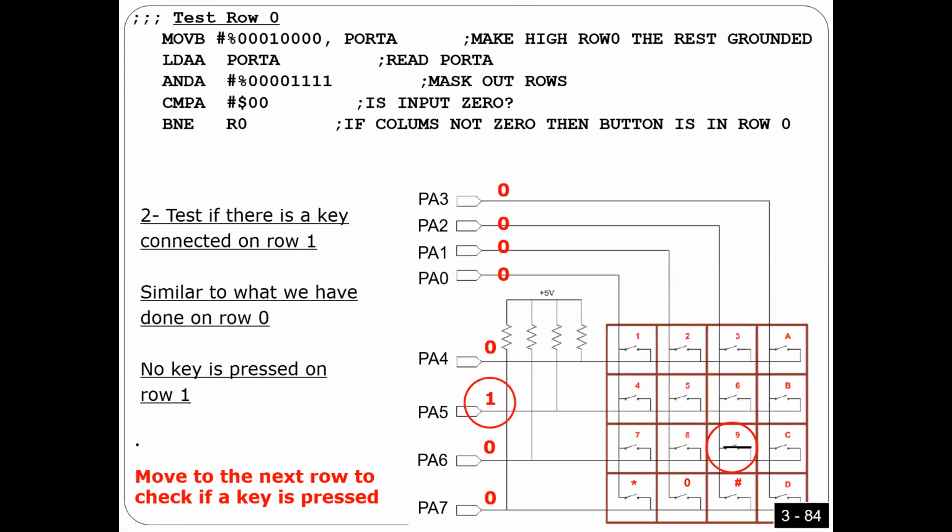As you see here, we have numbers from 0 to 9, but again, these are hexadecimal numbers. I'm talking about the decimal numbers, so between 0 and 9. Actually, what keypad is going to give you is ASCII, so a number from 30 to 39, right? So this is what the keypad is going to give you.